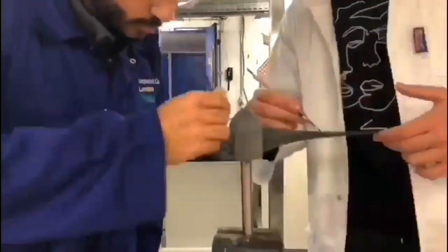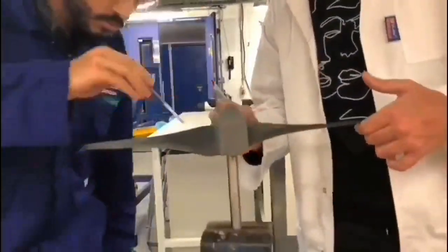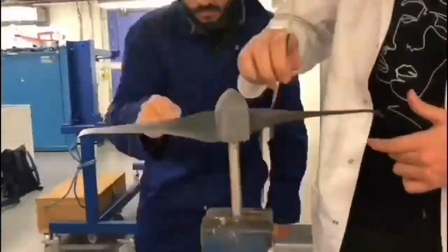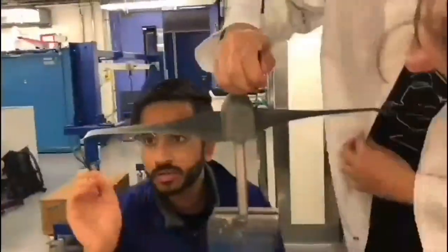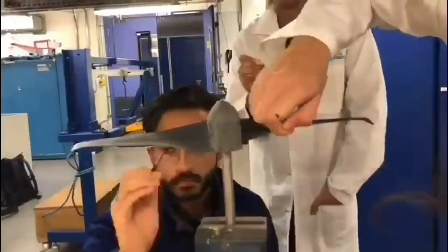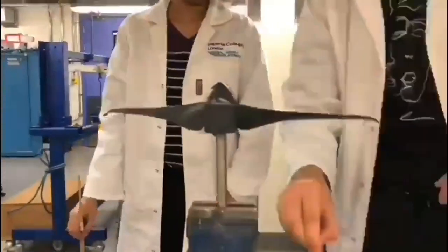The final stage of the manufacturing process was to coat the entire part in a thin layer of acetone. As a petroleum-based plastic, ABS is highly soluble in organic solvents such as acetone. The outer layer slowly dissolves and solidifies when the acetone evaporates, leaving behind a more uniform, stronger piece with fewer voids or scratches near the surface.